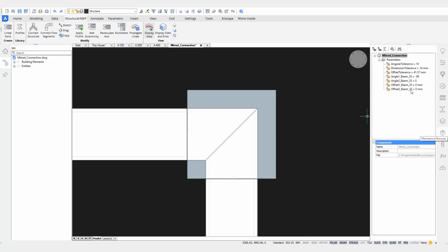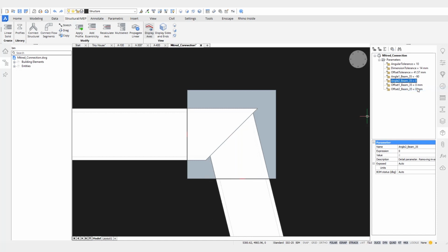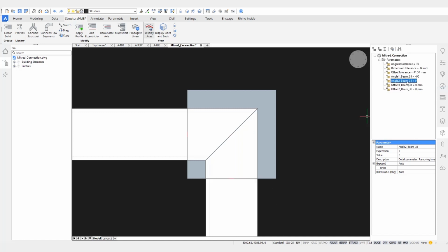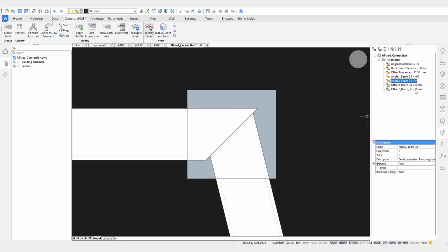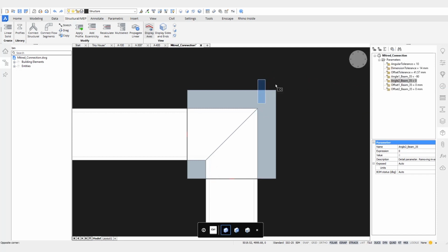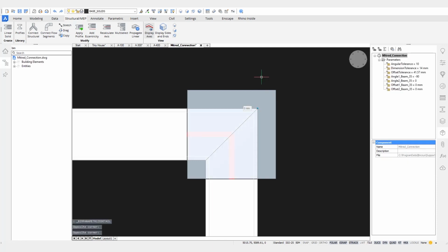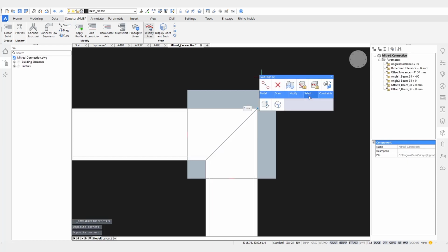And I can see now, just the same as with the door earlier, I can animate parameters to see what they do. And we see here when we animate this angle parameter, it doesn't really solve this really cleanly. These connections here at the corner aren't maintained. So I can still add some custom constraints myself. In this case, I'll just have to add a coincident constraint between 2 edges.